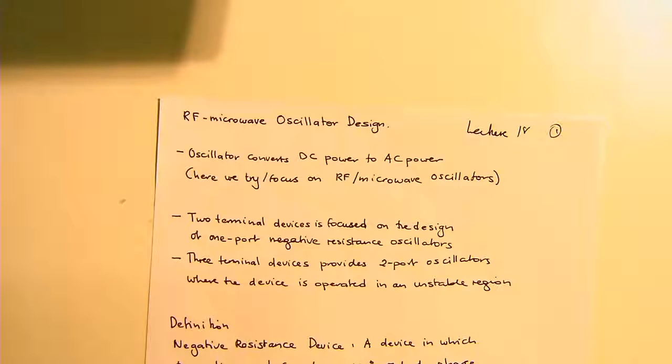So even though you think you've designed it for F0 nominally, it's usually at some other frequency, F delta. So what do you usually do to get it back here, to make sure it's all right? Has anyone heard of phase lock loops? Yeah. So rather than just having an oscillator, we've got to put a phase lock loop around this oscillator before we feed it into the mixer.